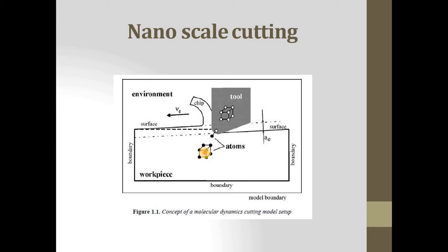So the more universal representation further allows you to go beyond the ideal single crystalline structure and also consider the polycrystalline defect structure, pre-machined or otherwise constrained workpiece models and nano smooth surfaces. So various applications specified by boundary conditions may be applied. In recent years, the number of applications considering quantum mechanics for the interaction between the atoms has been steadily increasing. However, here only the more classical atomistic approach will be presented.